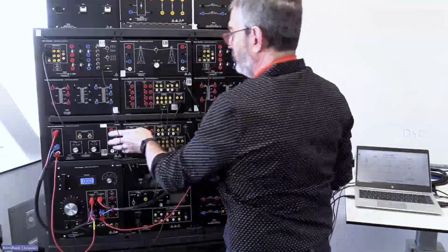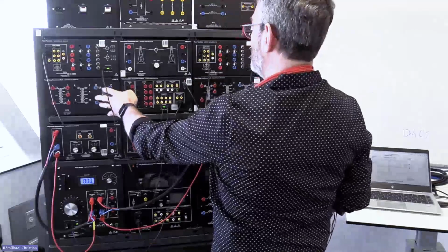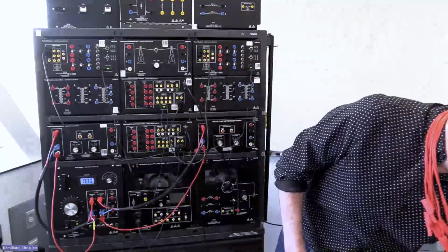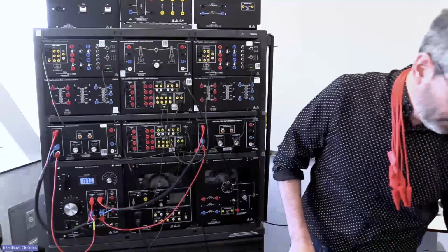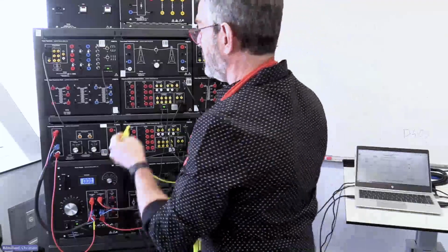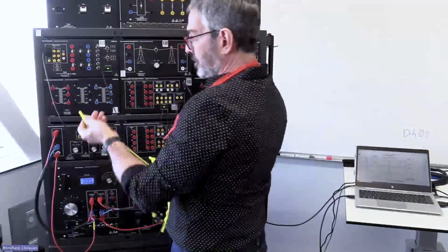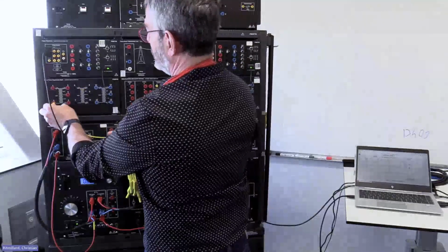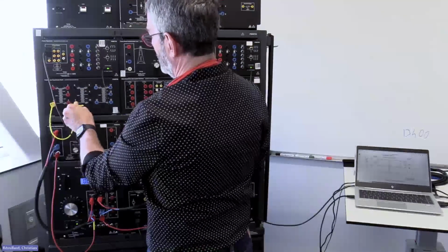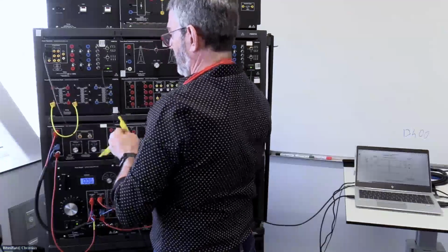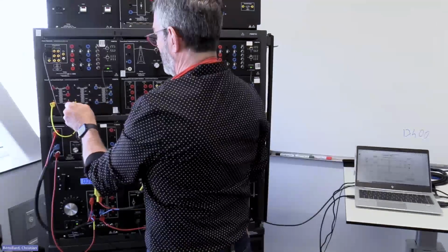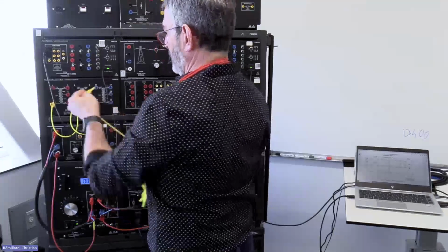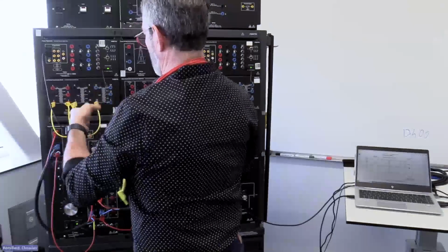Good. Then from our transformer, we will go to the three-phase transformer bank here, and these require a bunch of short wires to wire in a star-star setup. So that's what I will do now here, the primary being the left units here on each of my transformers. I will connect the 2 with 7 and the 12. Have the primary in a star pattern, and same thing for the secondary, 5, 10, and 15.